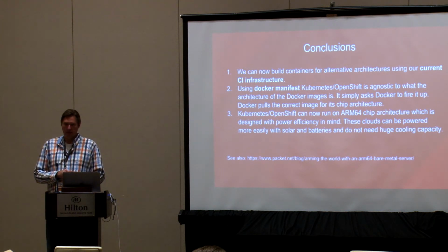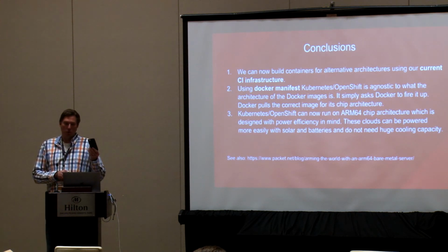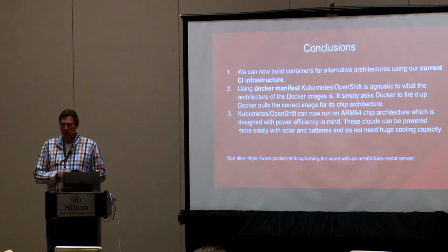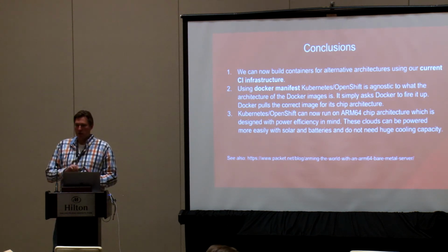What's the magnitude of energy saved? Well, it depends, obviously, but the ARM chips are designed for phones, and so the number one design criteria is low power. So it's in the order of 10%, I would say, compared to Intel. Typically these boards draw about a watt and a half. So it opens up the way to power them with solar panels.